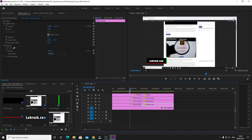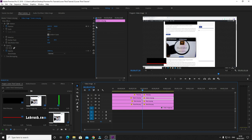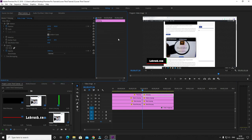Okay, you see it gets vanished quickly, or it gets invisible. The mistake I have done is I should have at least one frame here, okay. Anyways, it's very easy to remove it. Just select the keyframe and delete it, okay. So select the keyframe here and hit delete.